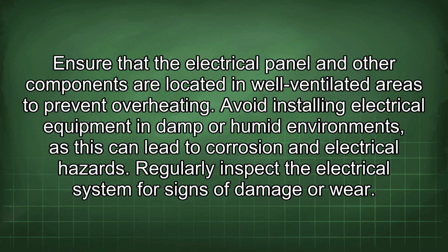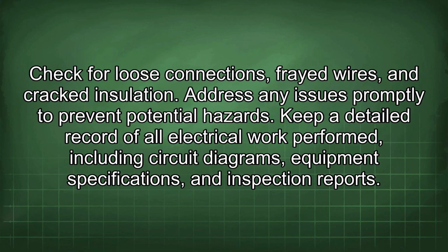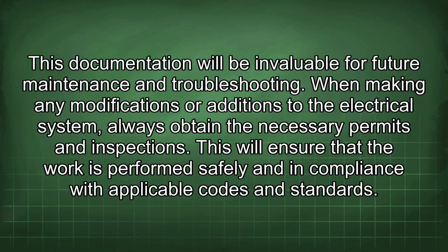Regularly inspect the electrical system for signs of damage or wear. Check for loose connections, frayed wires, and cracked insulation. Address any issues promptly to prevent potential hazards. Keep a detailed record of all electrical work performed, including circuit diagrams, equipment specifications, and inspection reports. This documentation will be invaluable for future maintenance and troubleshooting.